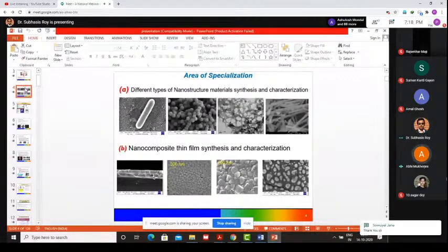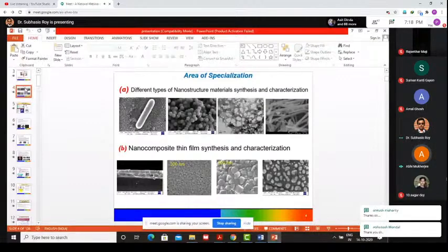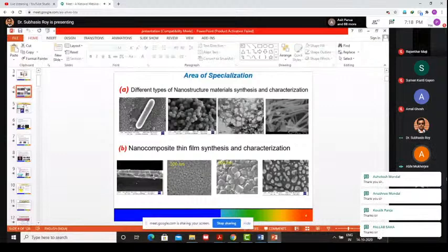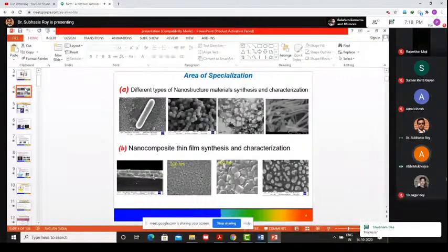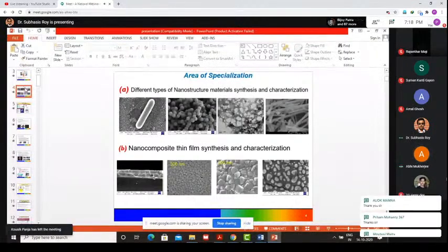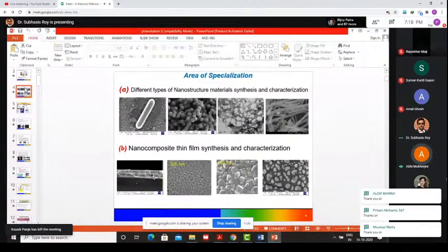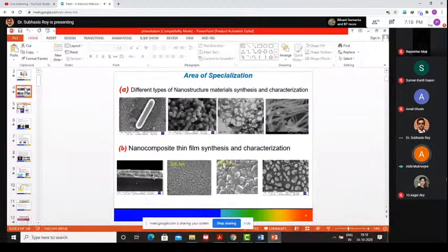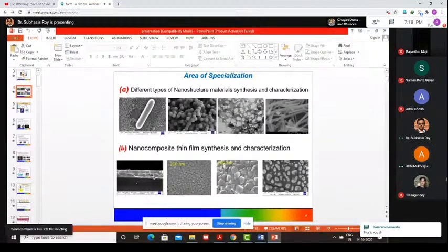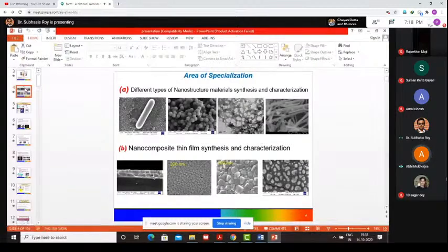Okay. Anyway, if I am audible, then I would like to ask you, in case of your solar cell, I have noticed that you have used indium tin oxide coated glass as a platform. As you know, nowadays the focus is mostly on flexible electronics. So if something like PET or, suppose, PDMS can be used as a platform, I have seen the annealing temperature is 80 degrees, I think PDMS will be fine, but will conductivity be an issue here?